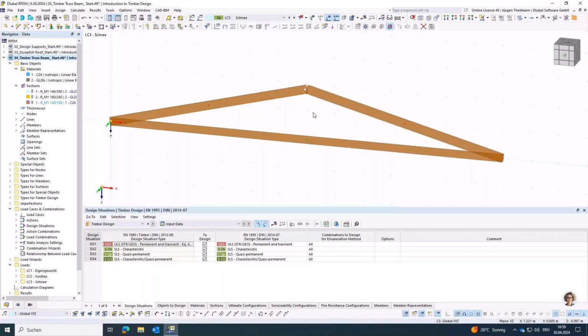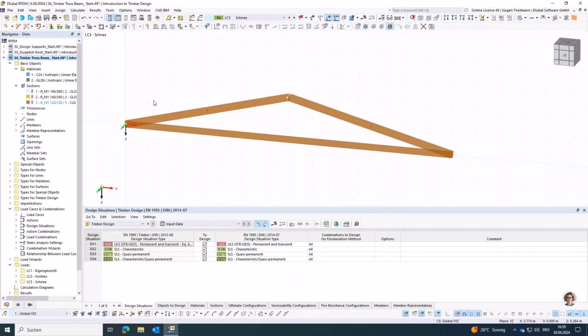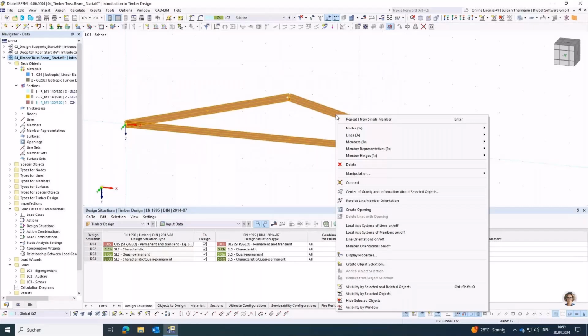Okay, this is now the hinge, and now we will need some intermediate points because I want to build the truss members in between those two girders. So now I select all of my members, make another member division. So we have 3 members selected.